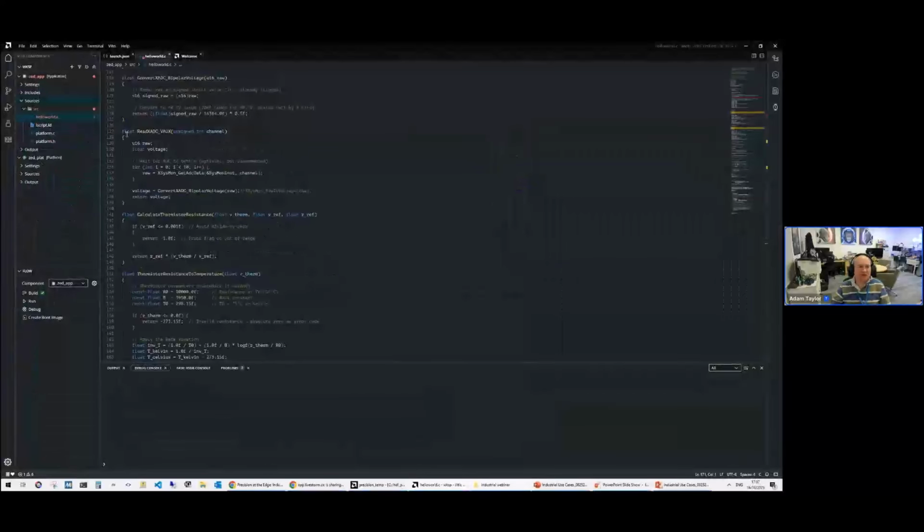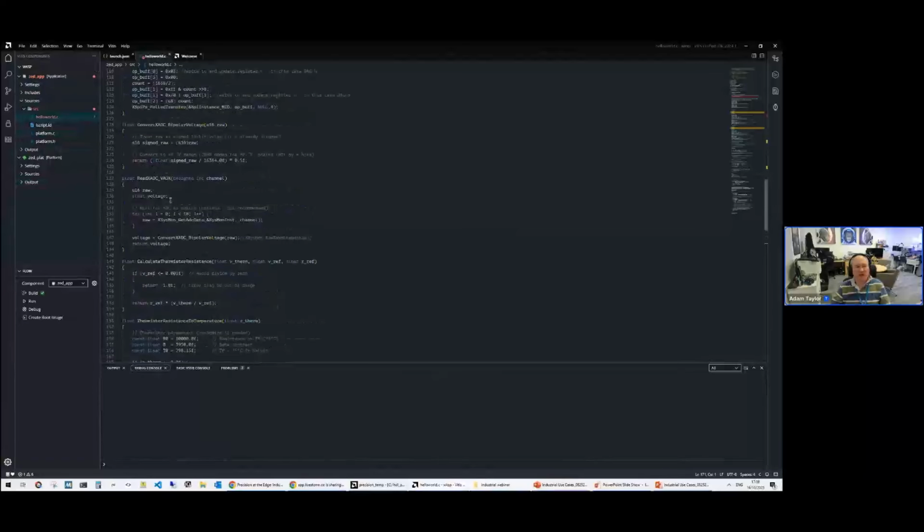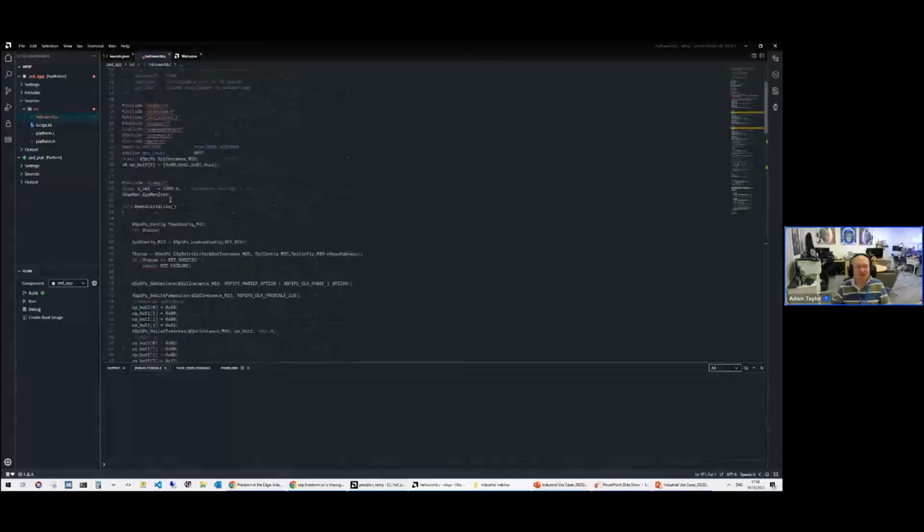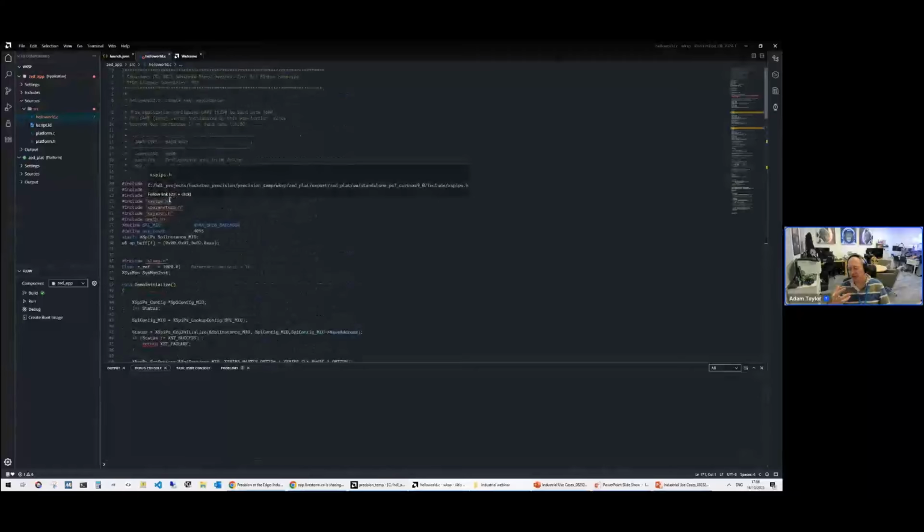And when we bring it over into our software world, what we want is to create an application. If we go up to the top, we create a platform with our exported XSA that's come from Vivado, and then we pull this into our Vitis application with that platform, and we create an embedded Vitis application on top of it.